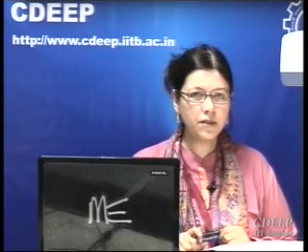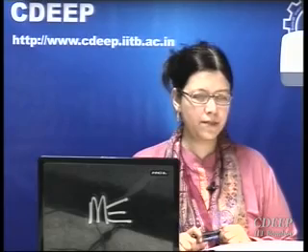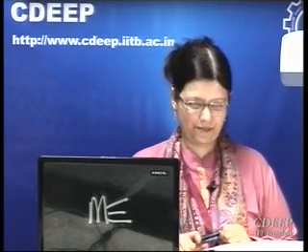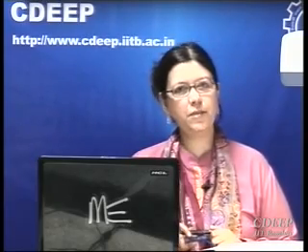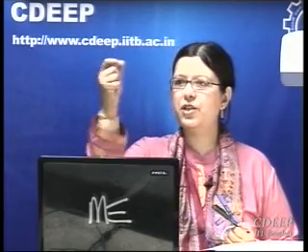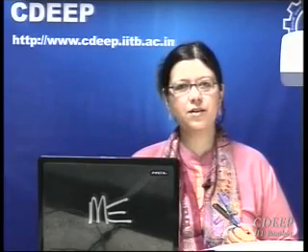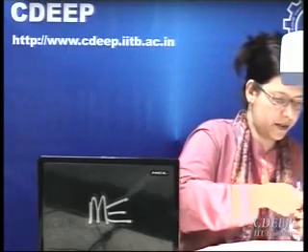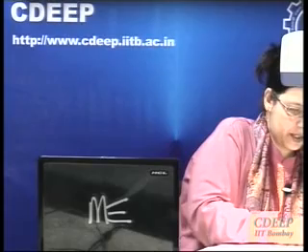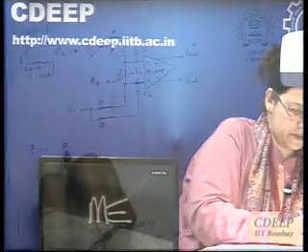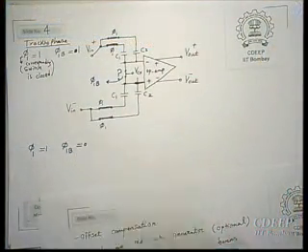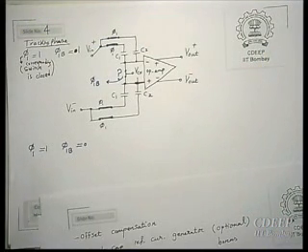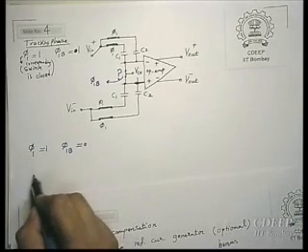If I don't take VCM, the bottom plate will be in a floating state, right? It will be a floating node. Therefore, there is no chance of charge injection. So therefore, phi 1b goes to 0 first. So you will have an intermediate state, which will be this. In this intermediate state, same as before, nothing happens. Nothing changes. But there will be no charge injection. And then now you will go to this stage.